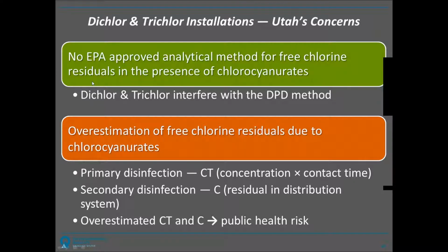One is currently there's no EPA approved analytical method for free chlorine residuals in the presence of chlorocyanurates, because of the interference created by dichlor and trichlor chemicals. And our second concern is the possibility of overestimation of free chlorine residual due to chlorocyanurates.